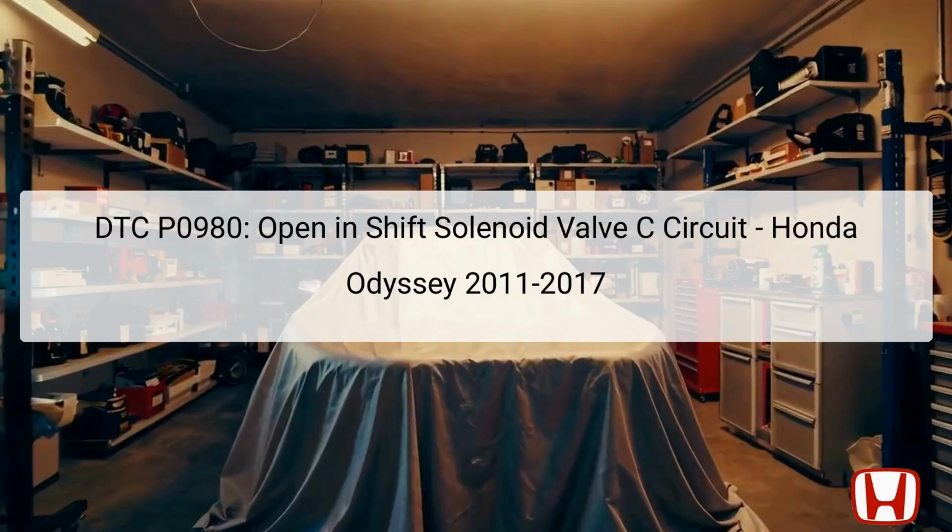The DTC P0980 indicates an open condition in the shift solenoid valve C circuit of the Honda Odyssey model years 2011 to 2017. This solenoid is crucial for the proper operation of the vehicle's transmission, particularly in ensuring that the transmission shifts smoothly between gears. The purpose of the shift solenoid is to control the flow of transmission fluid, which in turn facilitates engaging and disengaging gears to optimize performance.